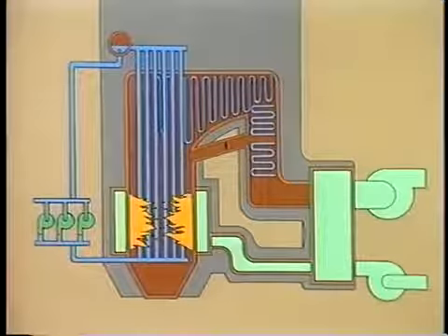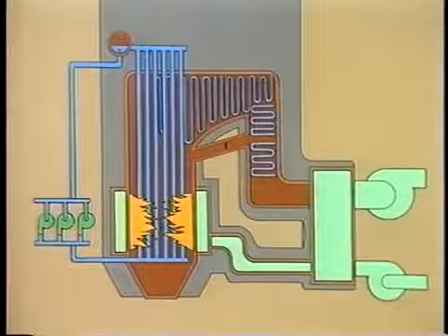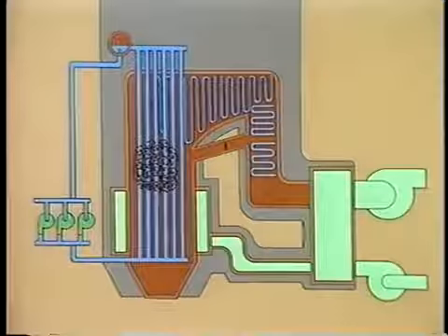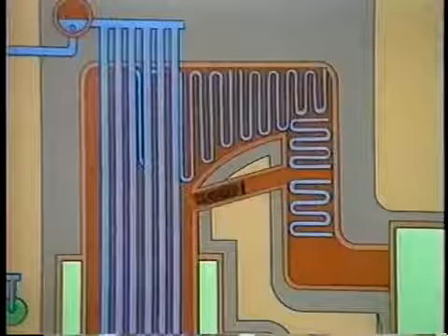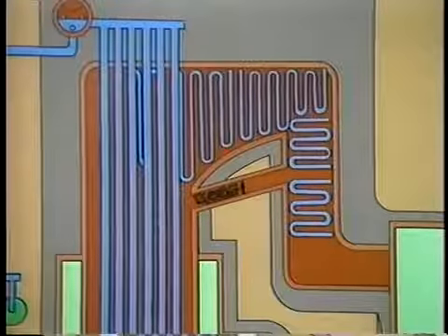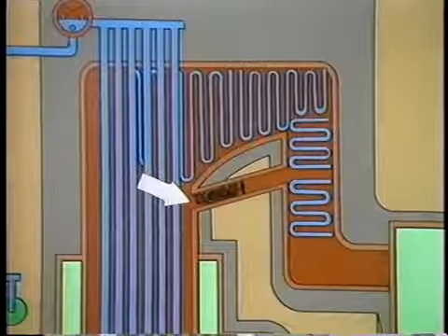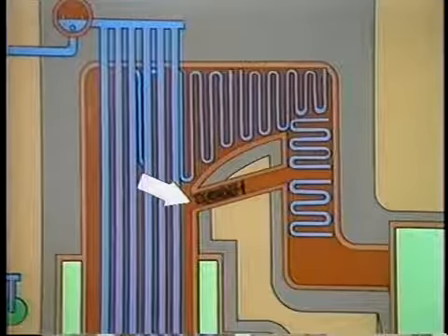Now, let us suppose that, for whatever reason, the boiler flame was momentarily lost and an abnormally large quantity of fuel entered the boiler. The operator responded properly by cutting fuel flow to the burners and increasing airflow to purge the boiler of all combustibles. But let us also suppose that a portion of the combustibles accumulated in this dead spot around the gas bypass damper and were not purged from the boiler.